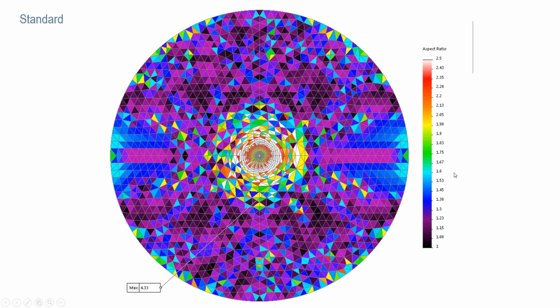So this is a very, very simple model here. I've just drawn a circular surface and punched a tiny hole in it, put a mesh control on it, so we can see how the standard measure does at giving us good aspect ratios. The aspect ratios aren't huge, but we want to try to keep them under 40 in many circumstances. They don't quite get up to that level, but if we compare the standard mesh to the curvature-based mesh,